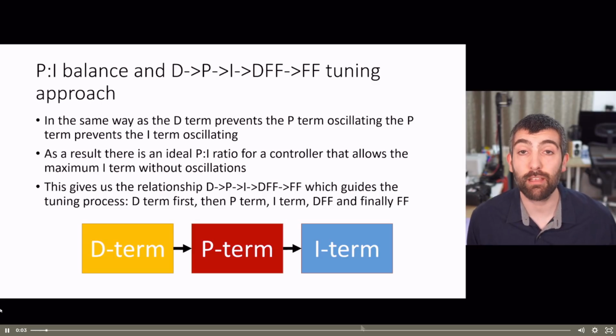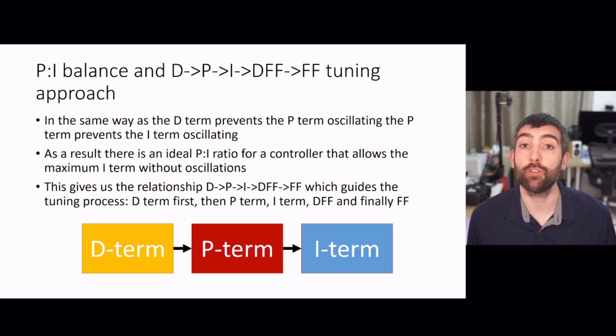Now that you've seen the theory behind all of the terms in the ArduPilot PID controller, it's time to give you an overview of the PID tuning methodology. We are going to be taking the tune in a certain order. We're going to start with the derivative term, move on to the proportional term, then do the integral term, before finishing off with the derivative feed-forward term and finally the feed-forward term.